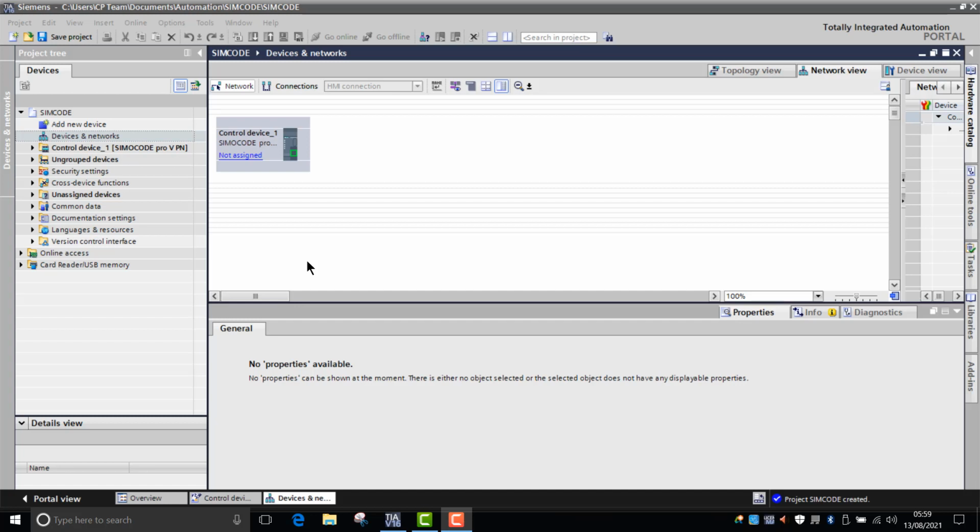When the actual ground fault occurs, the pathway to ground immediately becomes unrestricted with no resistance, and this causes a massive influx of current flow. When a ground fault causes a current spike in this way, the circuit breakers can trip and shut off the power, and it can also damage your motor. So the idea is that if you put preventative measures in by using this ground fault protection, it'll protect your system in a much more effective way. I'll show you how to use that.